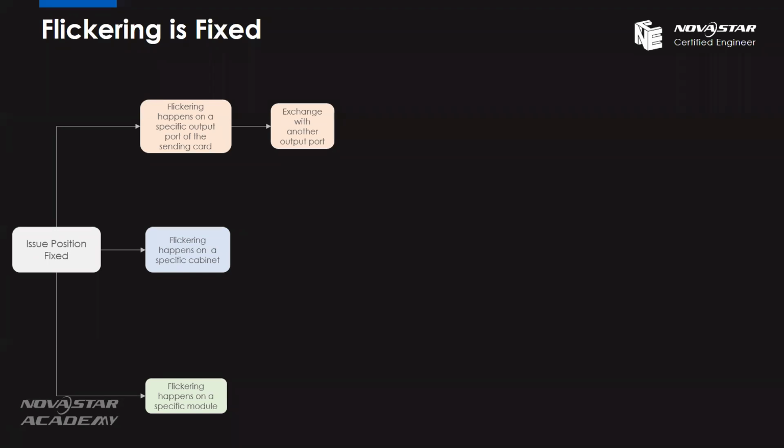We can exchange port 1 with port 2. If the problem stays on the same old output port, which means after we replace these cables the problem is still on this port loading area, we can confirm it's a sending card output port issue.